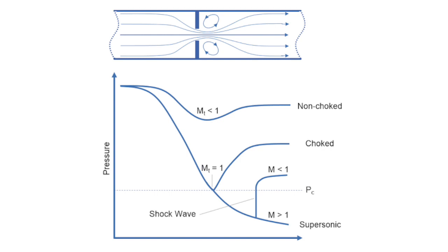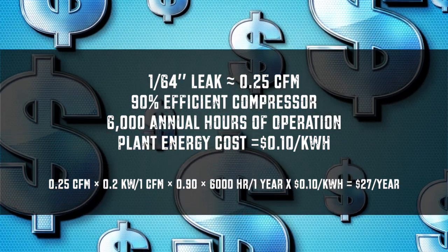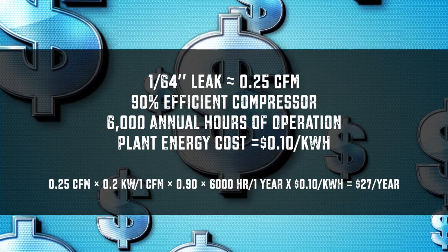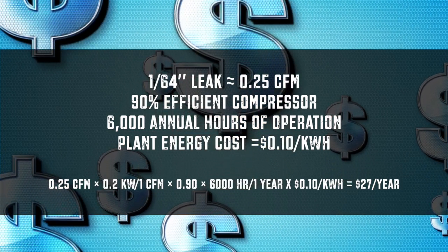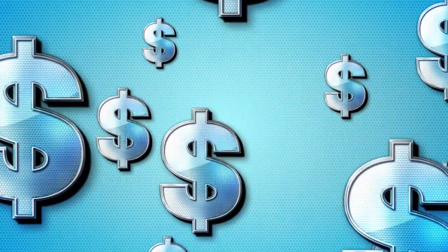The more you increase the size of the hole, the higher the flow rate through the leak. So you can estimate the losses for an air leak by guessing the size of the hole and the airflow through it. However, keep in mind this is not a perfectly accurate technique. It's also challenging to locate where leaks are.